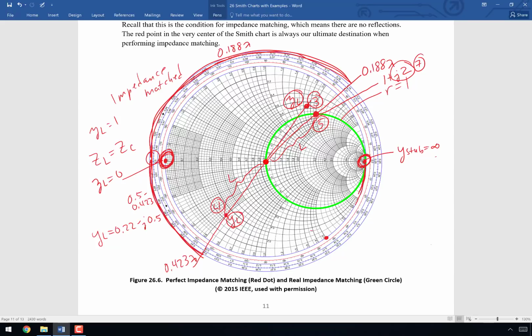I'm going to just go around the outer edge here. This is perfectly imaginary. There is no real impedance there. So I've gotten to negative J2. This point now corresponds to 0 minus J2. That negative J2 is going to cancel that positive J2.